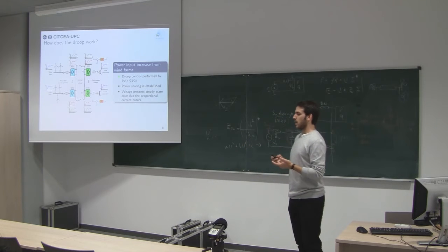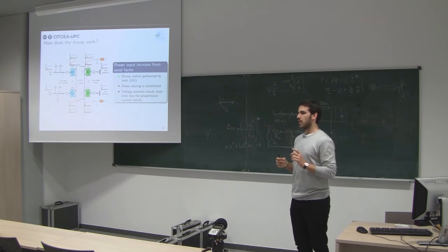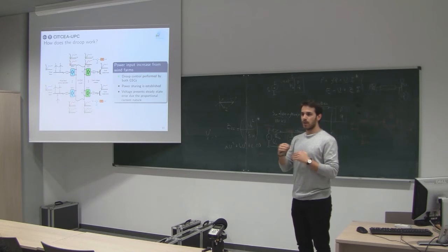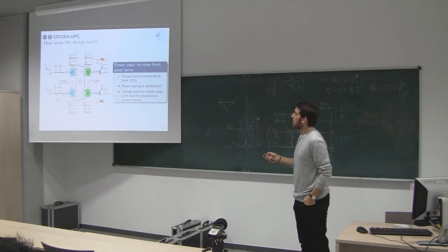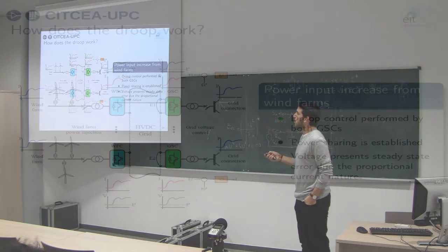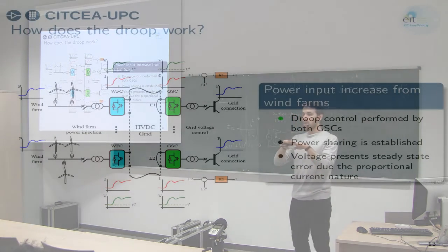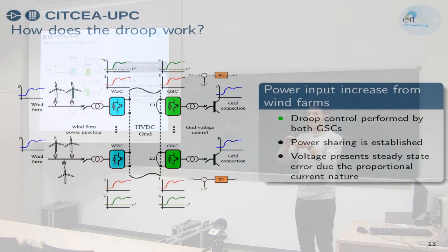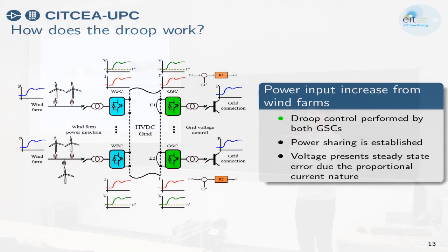So I would say that the droop control takes advantage of that deviation on the error in order to operate the system. Here you can see you have the reference, and the droop control will control the voltage of the grid with a certain error. You are assuming a deviation of plus or minus 5% on the grid. You have to assume that.